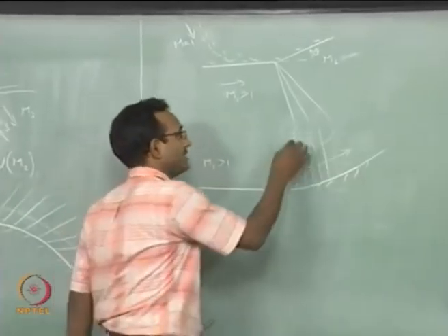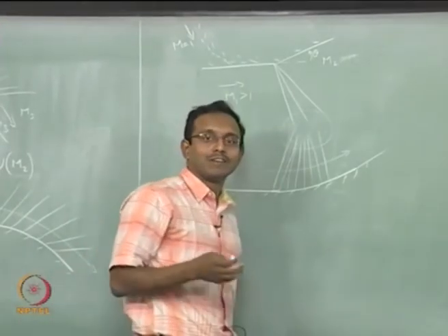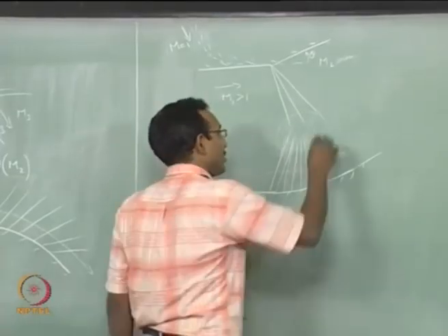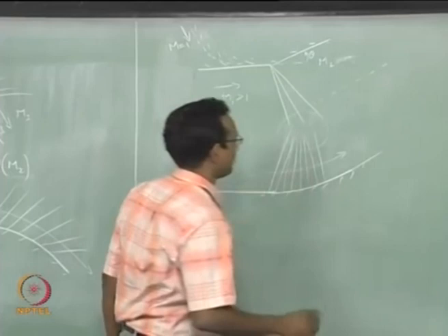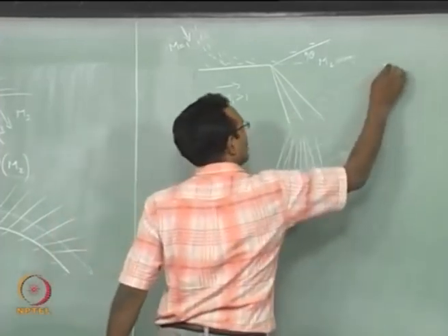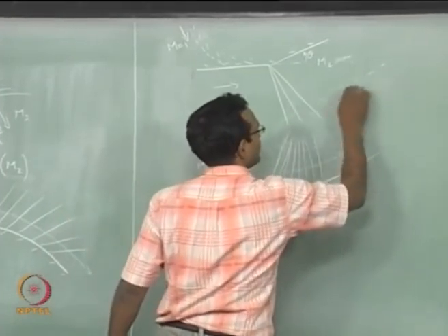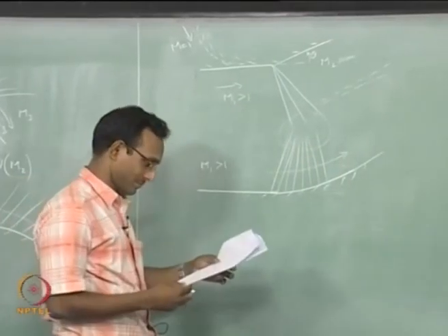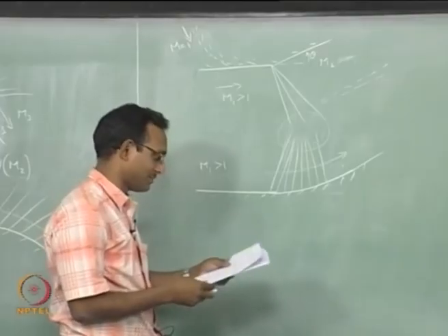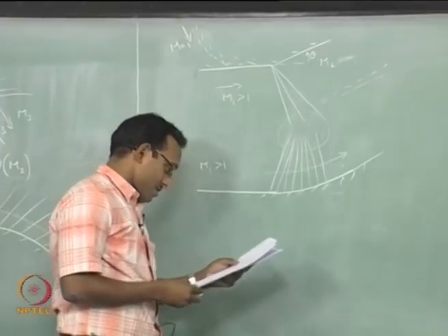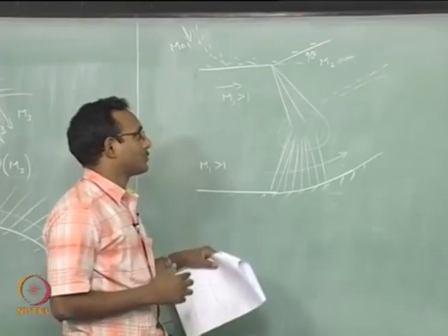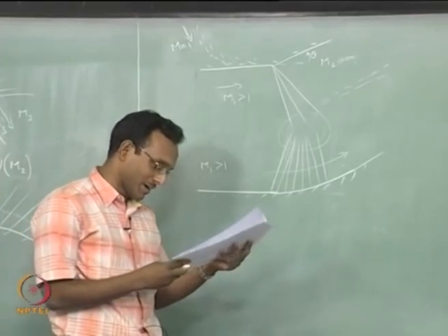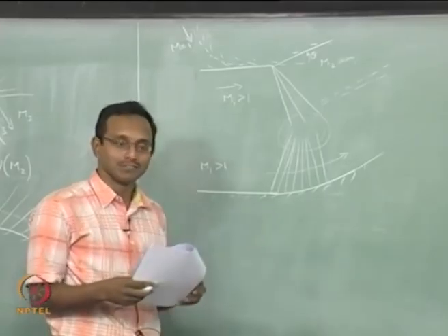But when these things interact, similar to what we did last time, when oblique shocks come and interact, they may form a slipstream kind of stuff. Here also there will be some slipstream forming here. Not just one slipstream, probably a whole bunch of slip regions might be formed out there. We will just ignore all that for now. I will show you pictures of that if needed. And so with this, I can now start solving problems. I can just tell what will be the Mach number, I can start predicting Mach number values.